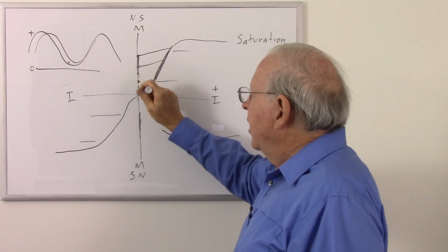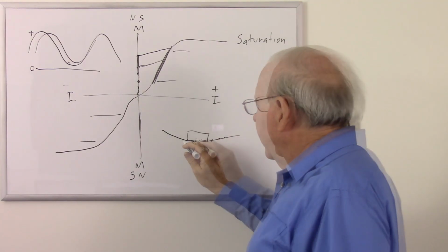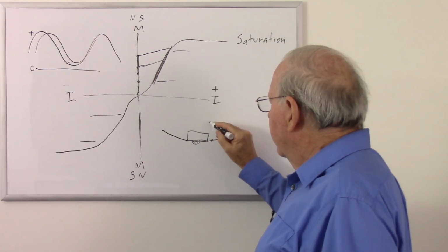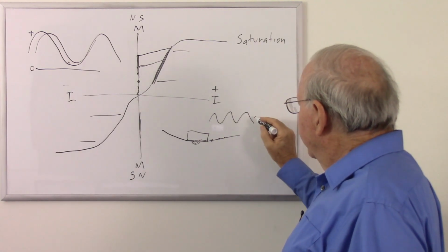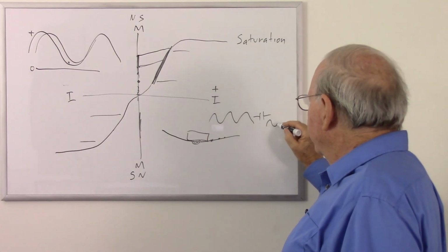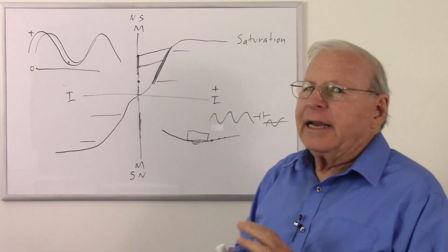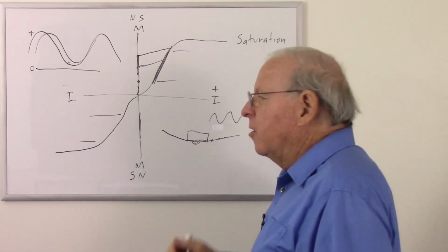Then the magnetism stays the same direction on the tape or the wire. As that goes by the head, our magnetic field is going to get stronger, weaker, and basically cause a current coming out of here that's stronger and weaker and stronger and weaker. And we can send that through a capacitor to pull it down to centering on 0 volts again. So, a fairly simple idea, except there's a problem with the medium we're recording on.